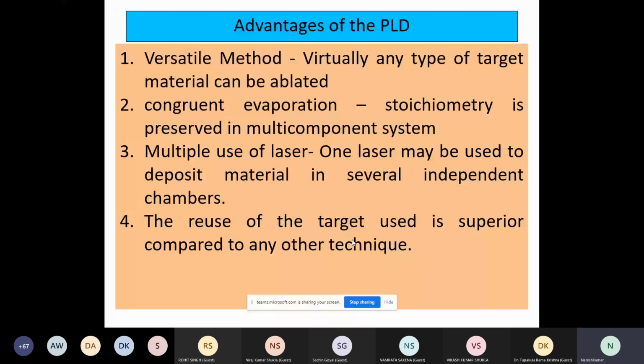Target one can easily use for the growth of thin film. Thickness can be of any type. So one can make such a small target easily, one thing. Secondly, to make a target, you require high quality, high purity oxide or powders, constant material, and high purity constant powders are expensive. So if you are preparing a target of smaller size, you need small volume, small mass of such expensive material. So that way your cost is going to be nominal.